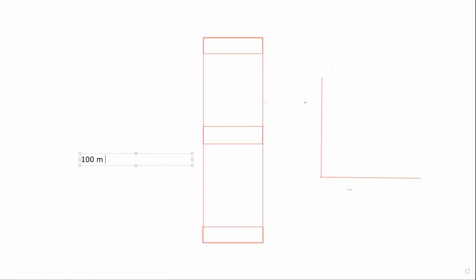So high rise means not only the building structure. Actually, whenever you are seeing any kind of structure that is cantilevered to the earth, right? Like see, we have this earth periphery, and earth periphery is generally round in shape, right? So every structure you are seeing, you have to analyze. The first stage is the study of their dynamics and vibrations, like their free mode vibration, that you have already taken classes for in modal analysis, right? When you go for a tall structure that is complicated, then we have to do this type of analysis, this pushover analysis, for collapse prevention.